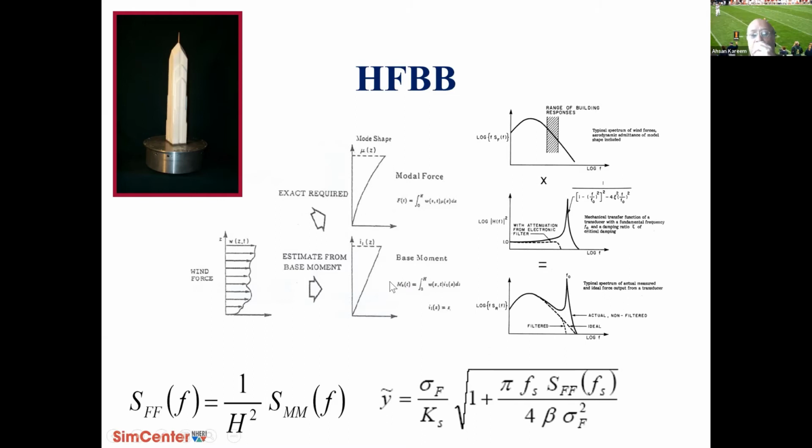And remember that the first mode has to be linear, not any arbitrary shape. Of course, there are ways to correct some of the things, and then one can get into this very standard random vibration approach in order to find out the mean square value of the response.